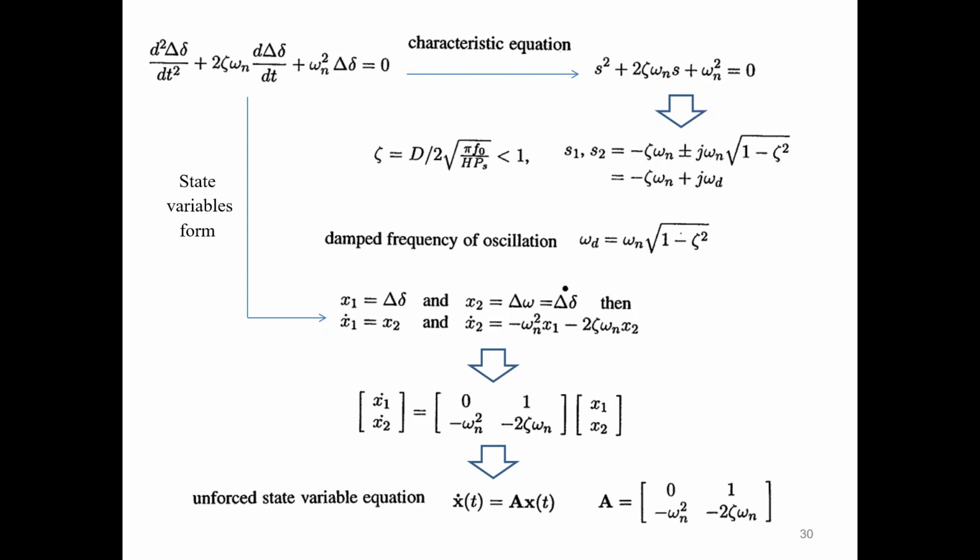If you have a zero root, it means that it's critically damped, and if you have two different positive real roots, meaning this term is greater than the rest, you get overdamped. You check from the square root here. Critically damped means 1 minus eta square is 0, so you get just one real root.